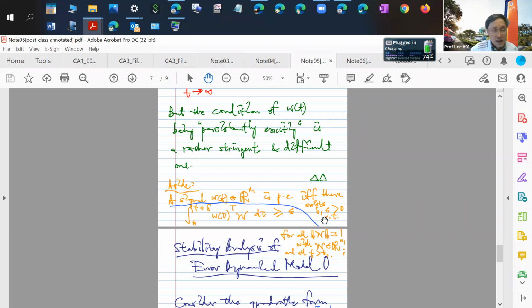then you don't have persistency of excitation. Persistency of excitation basically says that in this n space, your signals must all be moving around so that for any direction that I pick, there's always a minimum period of time for which there's a projection in that direction. And that, rigorously, is the concept of persistency of excitation.